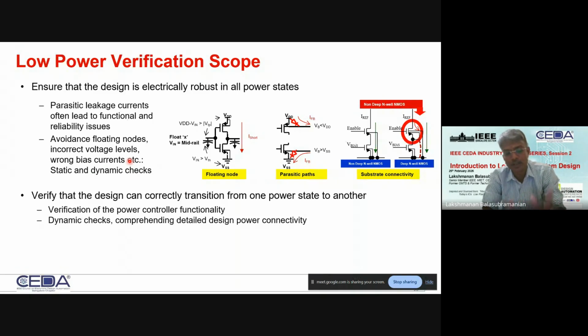So it's much more than in a normal RTL functional design, where you're only verifying functionality. Say you have an AND gate: you give all 4 possibilities of inputs A and B, and check whether your output Y is following your truth table, and whether the timing is meeting, the settling times are meeting your timing and performance requirements. Those are the primary 2 things.